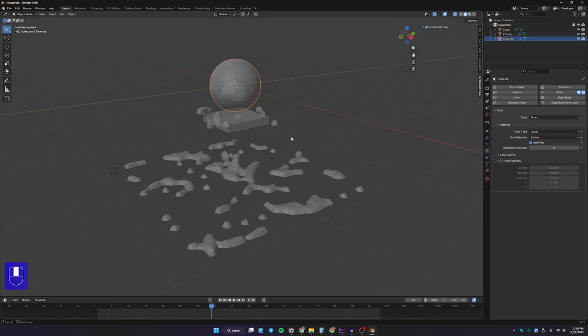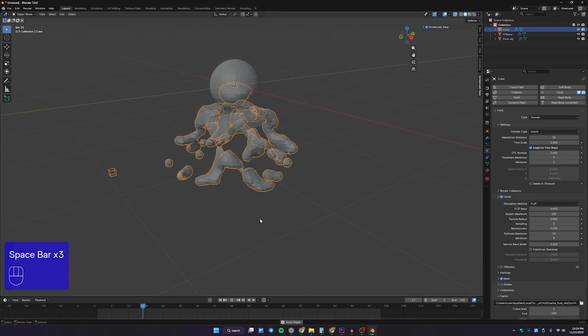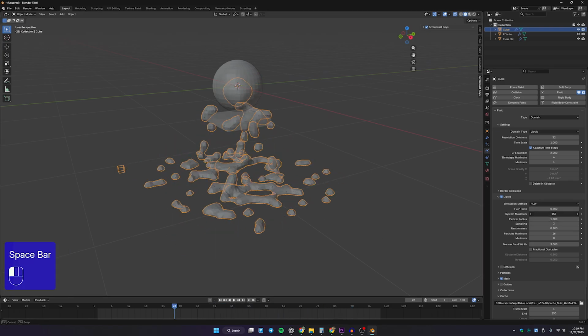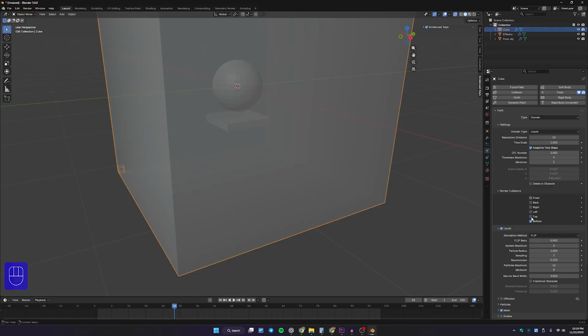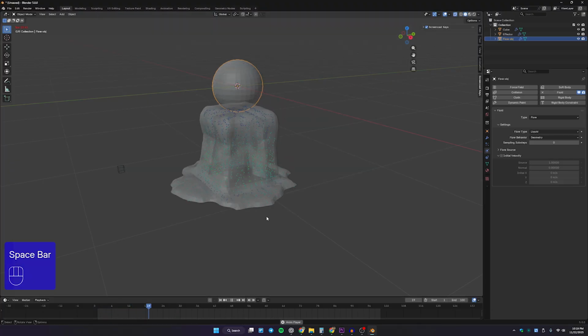Even though we set our flow object to inflow, creating the fluid continually, since my system maximum number is 150, it stops creating flow when it hits this number. So I'll set it to 0, uncheck these values, and change my flow behavior back to geometry, and then we can continue on.